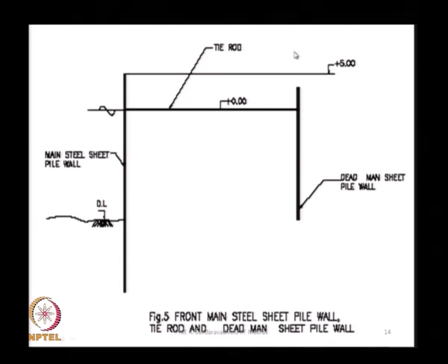About 50 kilonewton per meter square means about 5 meter of soil approximately, with submerged density, that is another 5 meter of soil here. That is what you are assuming to calculate the earth pressure. What is given in the code is you assume that the cargo is not stacked in this area, it is stacked only on the back side. That is what is to be assumed in the analysis.